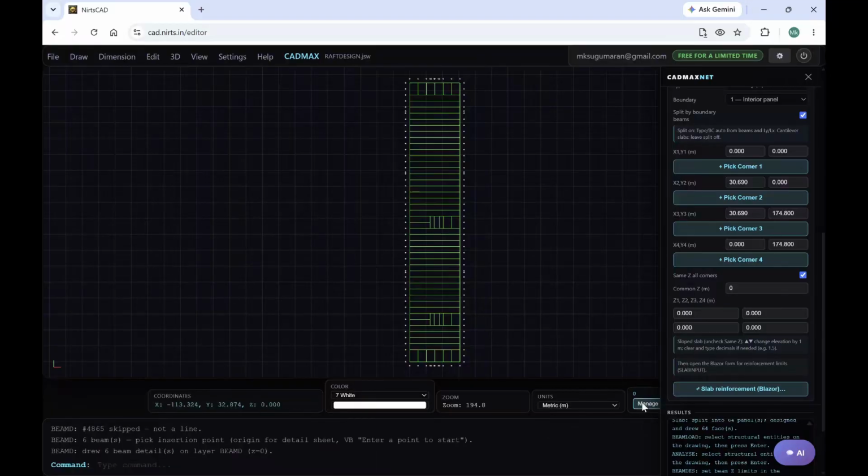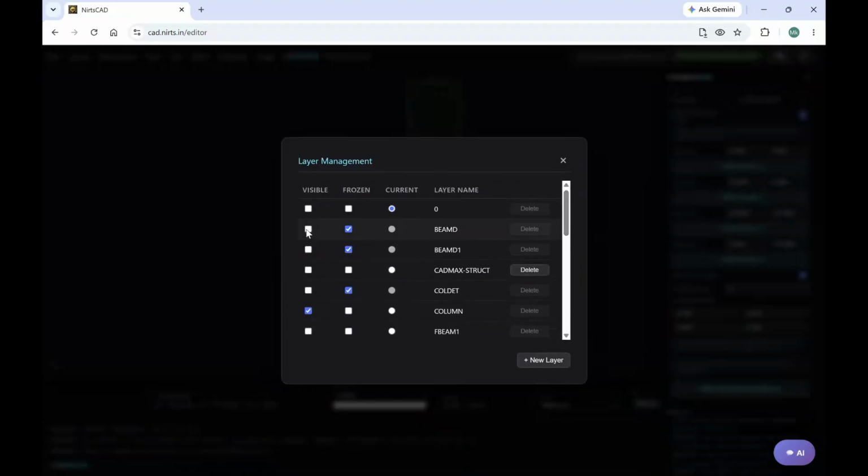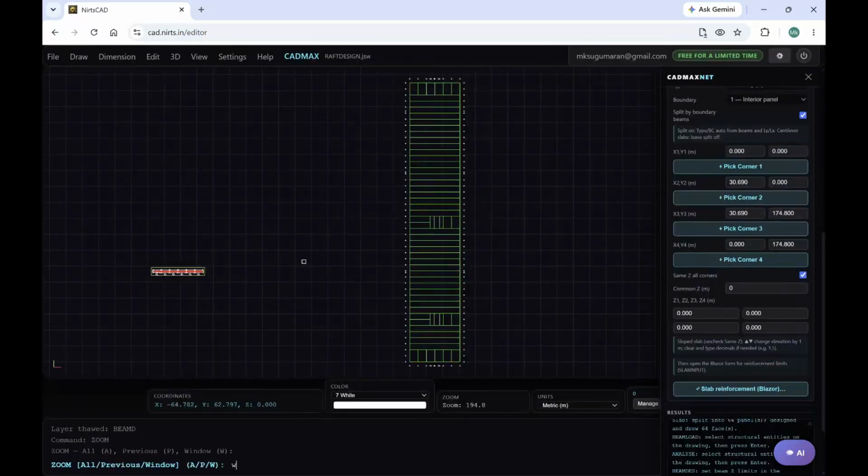You can see the reinforcement details are reversed as maximum mid-span moment will be towards upwards and corresponding reinforcement is provided. Number of legs of stirrups also drawn correctly.